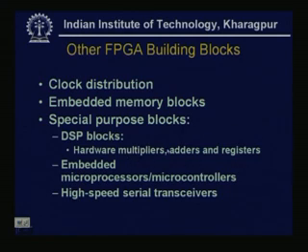So, they are treated as FPGA building blocks. Similarly, embedded microprocessors and microcontrollers are also treated as FPGA building blocks. So, nowadays though normally there are only 3 types of building blocks, one is programmable logic blocks, one is programmable interconnection, or sometimes we call it the switch box, and the programmable IO blocks.